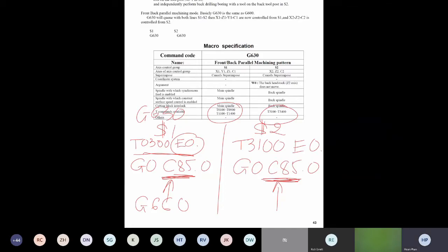Okay, I can see: when using the C axis to mill a radial slot, how do you implement the feed rate? Okay, I'm not quite understanding it, but let me try. When you're using the C-axis, the machine understands that you're going to engage the live tooling, and then you will have the main spindle locking. So right away the machine knows that the spindle is locked.